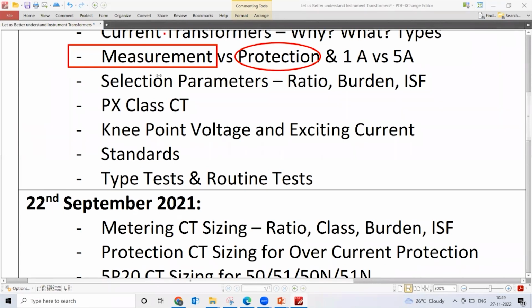And these voltage transformers and current transformers are basically inductive in nature. And the reactance of this inductance is proportional to the frequency, which means, for example, if there is a 23rd order harmonic, my CT offers 23 times higher reactance than what it offers to the fundamental frequency. And that's the input which is passed to the meter, and we are measuring the harmonics on the secondary, and we are claiming that it will be the same as what's reflected by the same ratio in the primary. That's not really logical, right? If you got what I'm trying to say, just say so in chat.